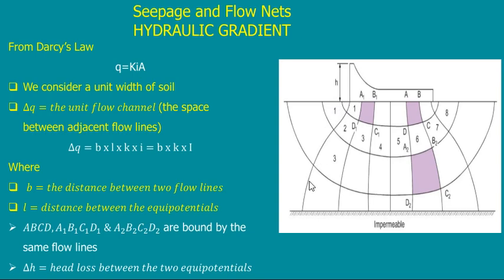Okay, I draw this line. Of course, the end will be perpendicular to this line because this line is also a flow line. So this equipotential line should be perpendicular to this flow line. If I want to draw the next one, where should I take it? This will be very easy. Why? Because you have this line, you have this line, you have this line. It is this new line that you want to add.